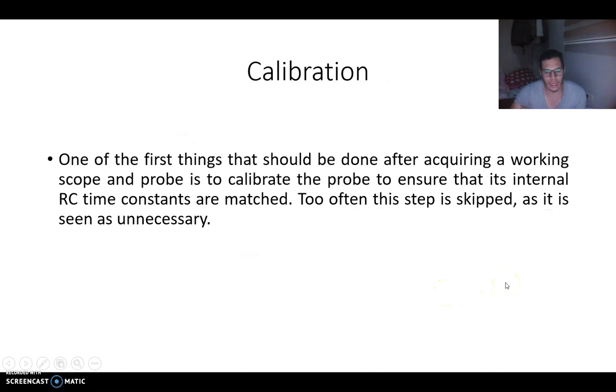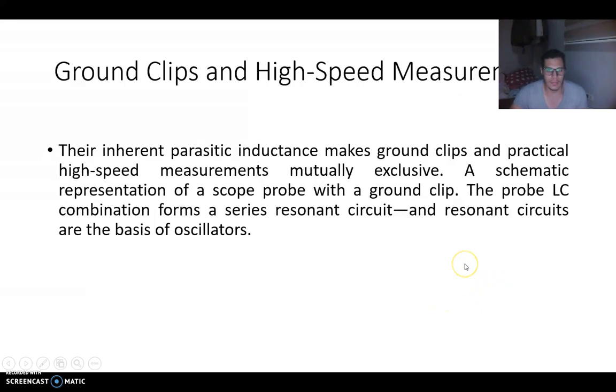Calibration: one of the first things that should be done after acquiring a working scope and probe is to calibrate the probe to ensure that its internal RC time constants are matched. Too often this step is skipped and seen as unnecessary.